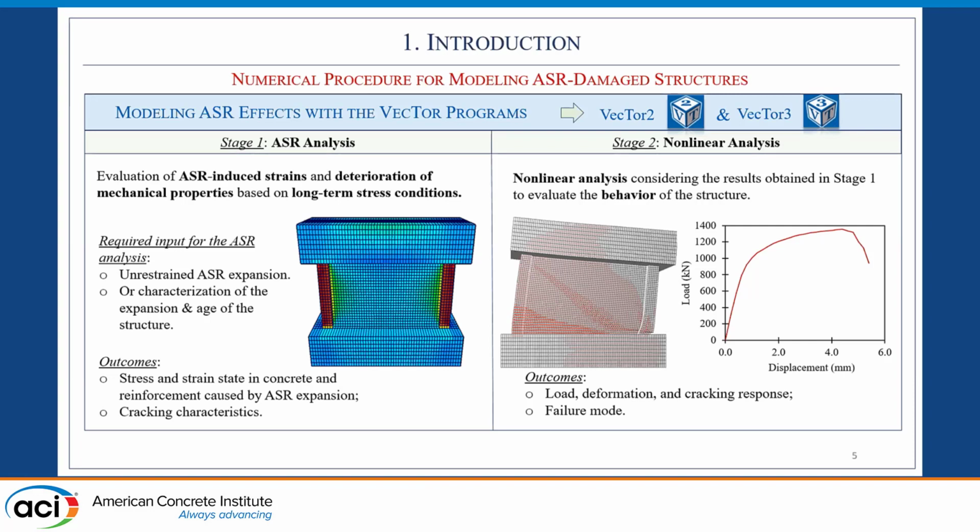In the first stage of the analysis, the goal is to evaluate the ASR-induced strains and the deterioration of the mechanical properties based on long-term stress conditions. Because the ASR-induced expansion is highly influenced by the compressive stresses that are developing under long-term conditions, we need to be mindful in this stage of the analysis to only consider the long-term sustained stresses.